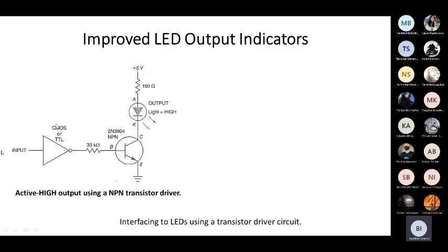First of all, we use a transistor when we don't want current to go through our integrated circuit. Here you can see some high resistance, which means there will not be too much current through this resistor. Second, it may not be an LED, it may be some other kind of output device that can take a lot of current, and we do not want too much current going through our integrated circuit. For this reason, we can use this transistor, and all of the current will go through the transistor.